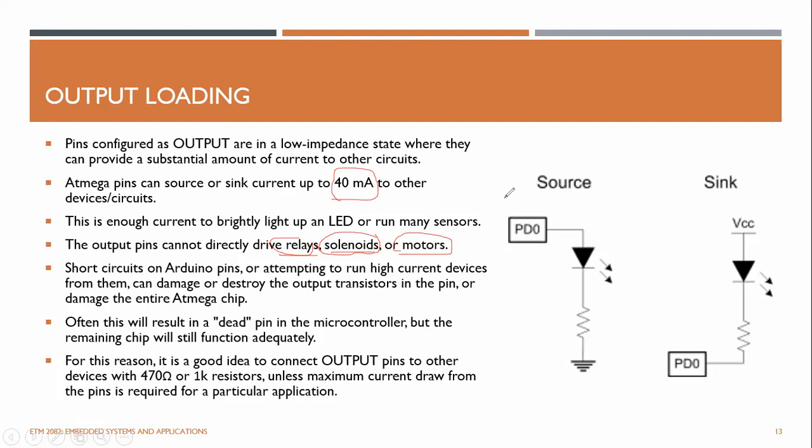So in this case, if it is 0 volt, nothing will happen. If it is 5 volt, the 5 volt will go through this diode and it will light up. Here, if you put 5 volt, and here again 5 volt, there is no voltage difference, so the LED is off. If you put 0 volt here, with again the 5 volt power supply, now the current can go from the high voltage potential to the lowest through here and through the ground, right? So now the LED will light up.